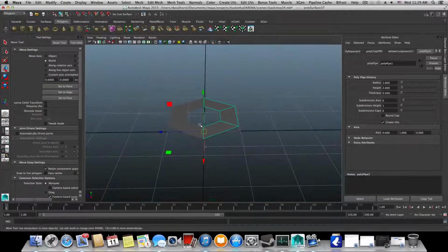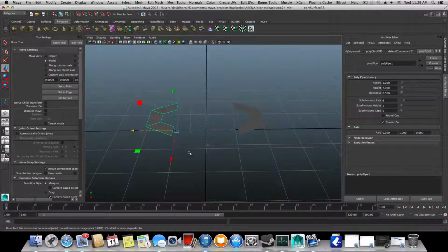What you want to do here is hold down the X key. Okay, so this cube here will turn into a circle. The X key, C key, and V key are three snap features. Okay, see those three blinkings there. We need the X, which is snap to grid, and when you push this, it will snap to this grid line. You want to do the same to this one and move it over here. So hold down the X and push it there.